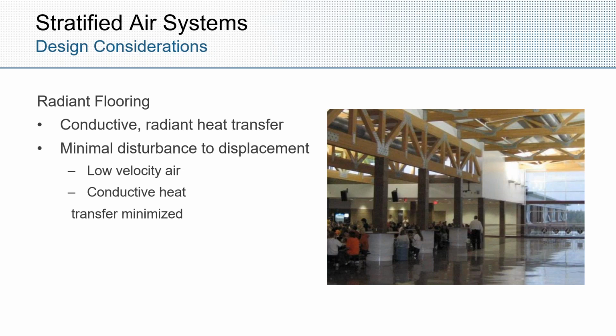There is a temperature of the floor that you're going to want to limit to, 82 degrees Fahrenheit, somewhere around there, so you're not having too much heat, which would end up warming the air enough to affect it once it gets 15, 20 feet away from the diffuser.